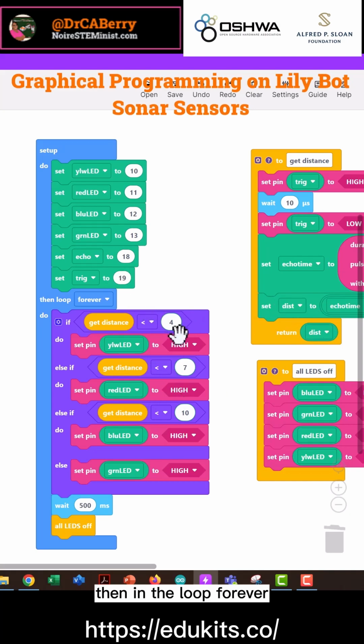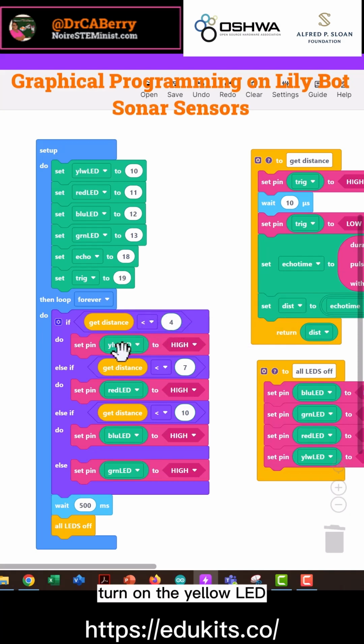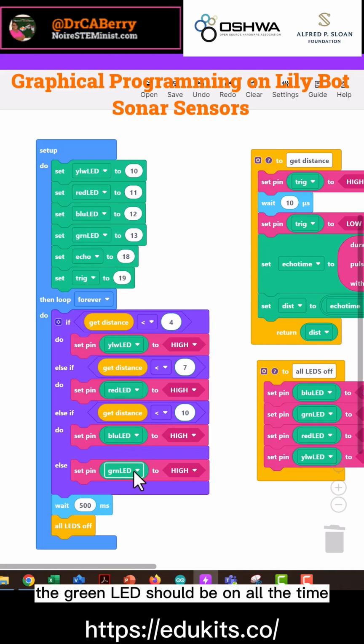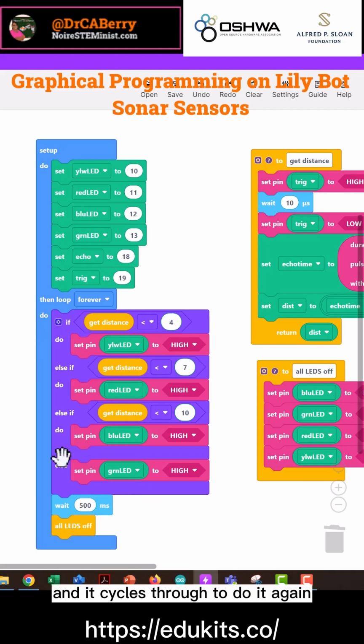Then in the loop forever, we're going to read our get distance, and if it's less than 4 inches, turn on the yellow LED. If it's less than 7 inches, turn on the red LED. Less than 10 inches, turn on the blue LED. And if it's greater than 10, the green LED should be on all the time. And then every half second, all the LEDs turn off and it cycles through to do it again.